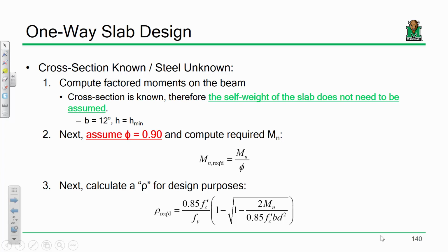We've been doing beam designs, and we'll design for a moment of 300 foot-kip or 250 foot-kip or something like that. But for a slab, when you're looking at that strip, it might be a moment of like 3 foot-kip or 4 foot-kip because it's such a small strip, and there's just not much load on that individual strip. But again, the slab itself is really small. So you're dealing with really small moments, but you're also dealing with a really small section. So it all balances out.